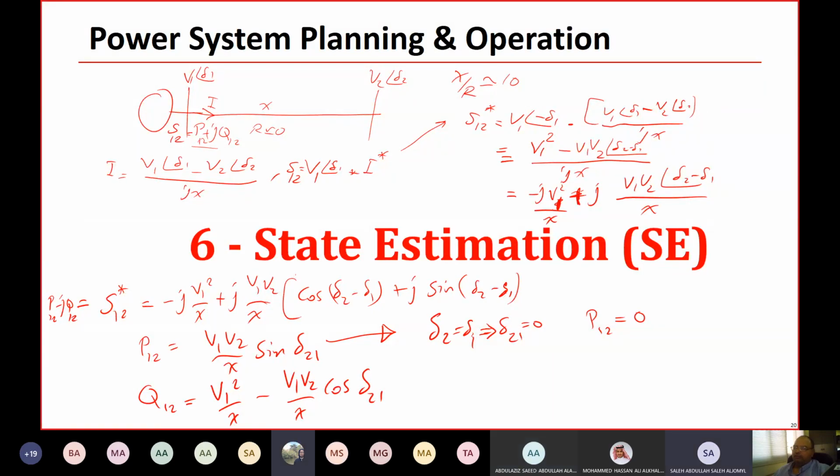Our target should be... no, why is it very bad? If the line flow is very low, for the current situation you have very low line loading. Is it good or bad? Do you want the transmission line to be heavily loaded? Would it make you happy for the transmission line to be at its limit? No. If the transmission line is 100 MVA loading, and I am running only 10 and feeding my load, is that good or bad? 10 is good.